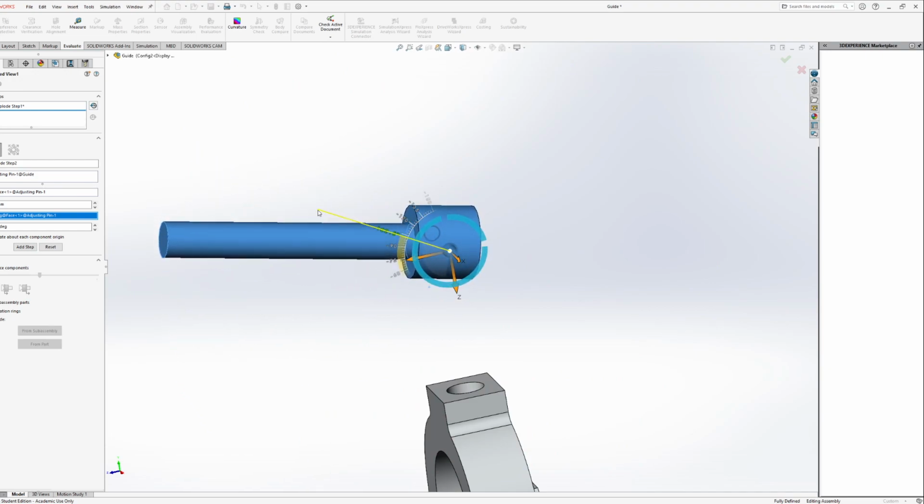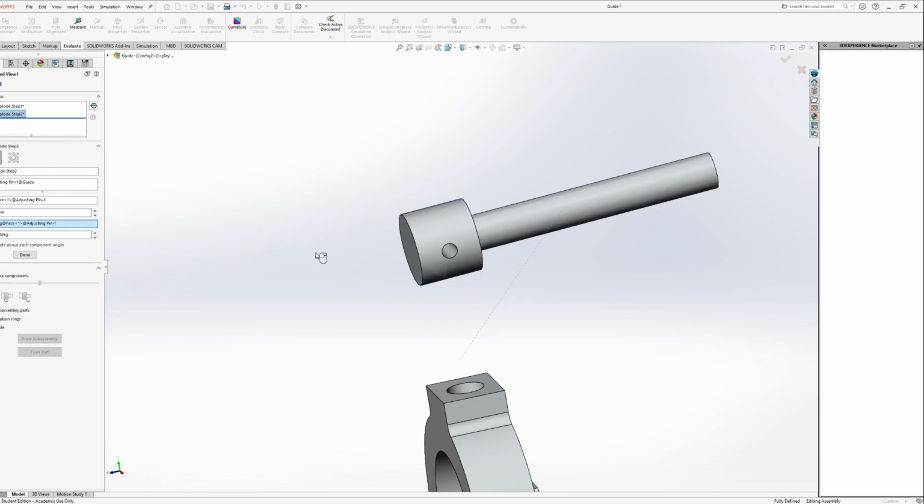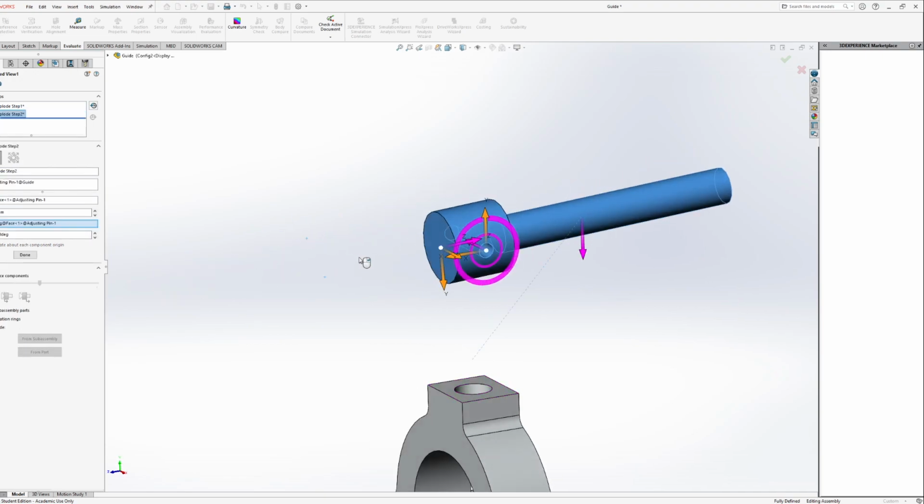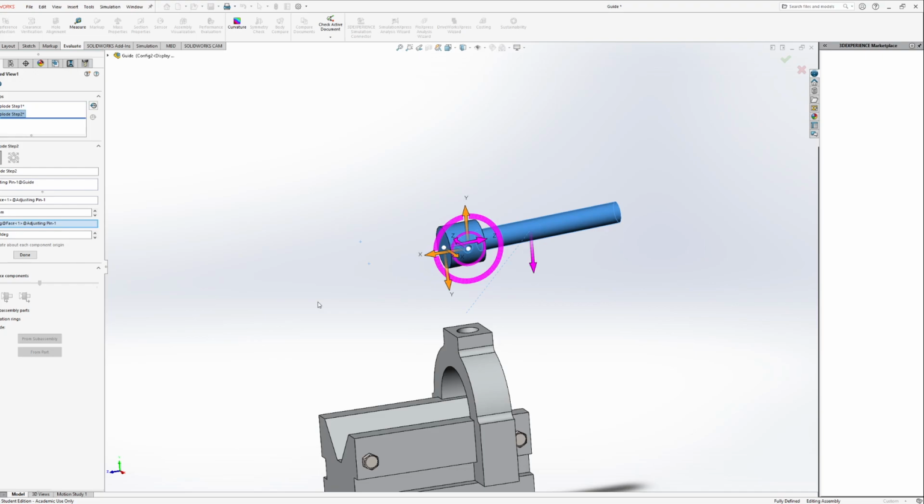What you can do in the case of the mailbox is you would just need to say, okay, well, I want to ensure that it's rotating about the pin, the cover pin, to make sure that it's only rotating as though it were opening up. Does that kind of make sense? Yeah, it makes sense. Okay. I didn't know you could select the point where it pivots.